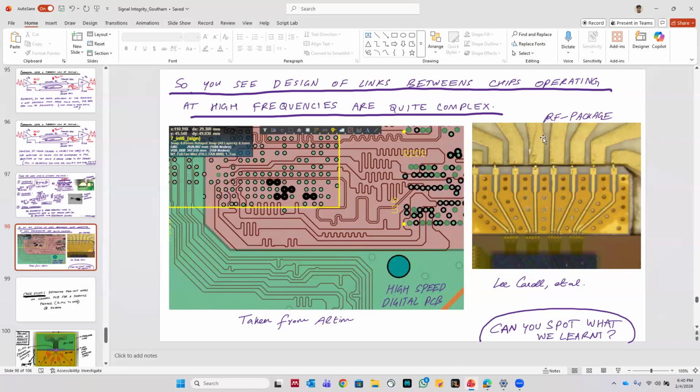So in very high frequency packages like 100 or 200 gigahertz plus, or even 50 gigahertz plus, you cannot have very sharp changes. If you see here, all the lines are varying very gradually, right? This is called an adiabatic kind of structure. Everything varies gradually to minimize reflections.